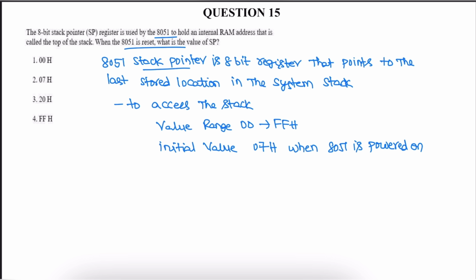So 07H when 8051 is powered on. The stack pointer is initialized to the value 07H when the 8051 microcontroller is reset, and data can be stored to the stack from 08H onwards. It is incremented by 1 when data is pushed onto the stack. Next question.